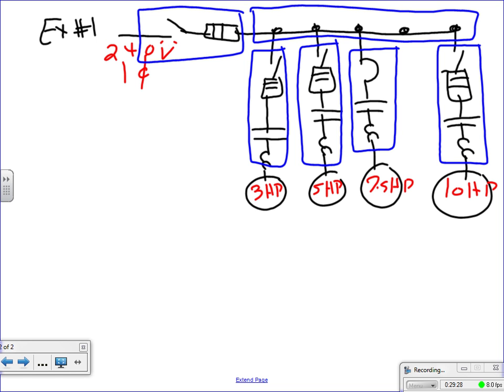You have one box for the disconnect switch for the feeder, one for the gutter. Everybody knows what a gutter is? Bring your cable and tie them together, splice them, and tap into all these 3 motors. This is one way of doing business. Instead, what's the alternative? Feed them from a panel directly. What's the advantage of this? Cheap.